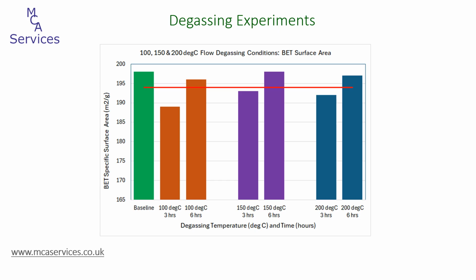This is quite an important point, as usually it's only the lower part of the tube that's heated, so the vapors will then have a tendency to condense on the cooler upper section of the tube rather than being driven completely out. For heavily contaminated samples such as these, it's then up to the operator to monitor this and remove any condensed material manually.